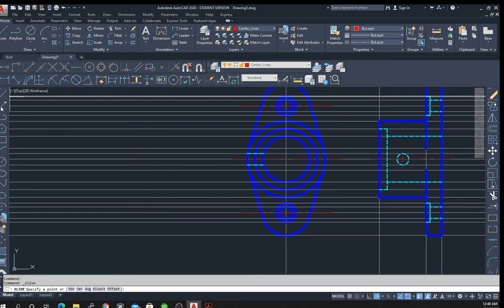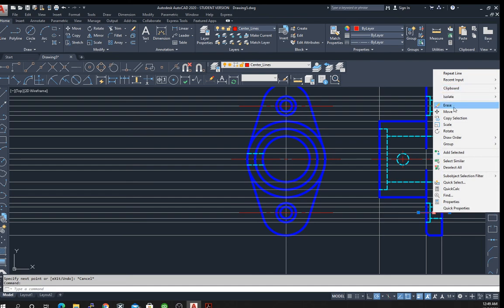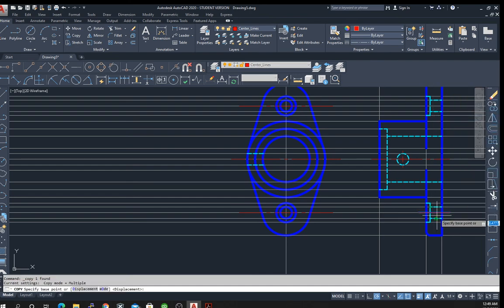So we can come back, start here, move out by 0.25. Oh, wrong line. Start here, move out by 0.25, and then make a 1 inch line. And then we could actually take this and copy it from that point and move it up.